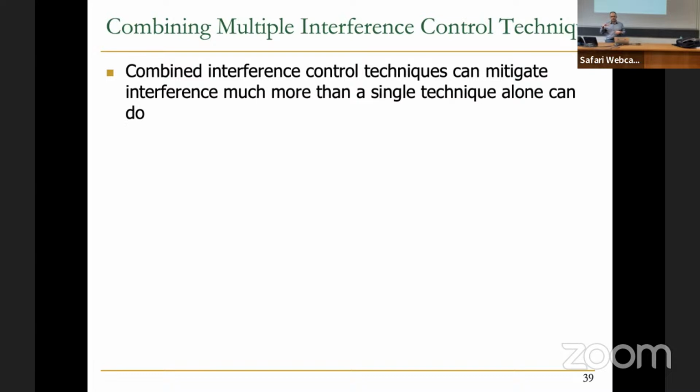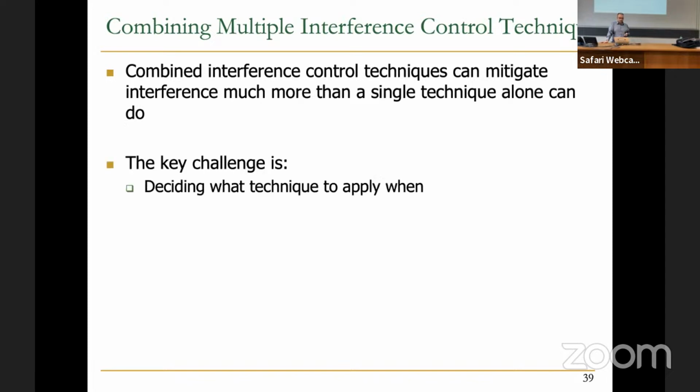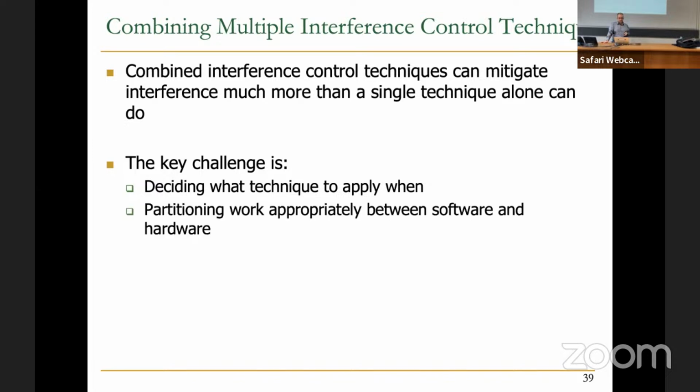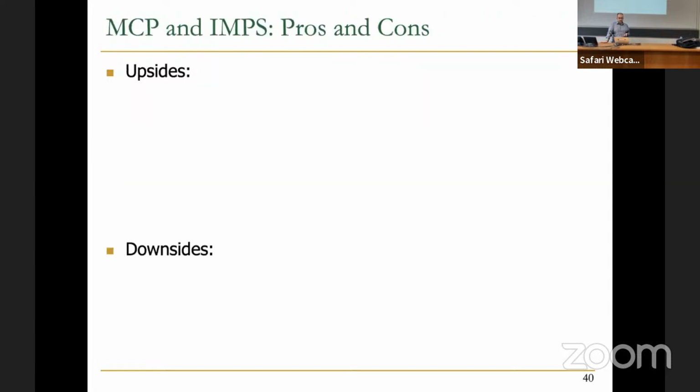Now you see that we had this memory partitioning technique, like channel partitioning, and that provides some performance, but at the same time, we observe that when we combine it with a scheduling technique, you can actually get much better performance. So it's always good to think about combining different ideas or techniques such that you can hopefully combine the good capabilities of them. But there are some key challenges, of course, like deciding what technique to apply when, or partitioning work appropriately between software and hardware.